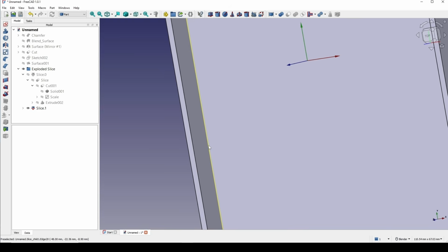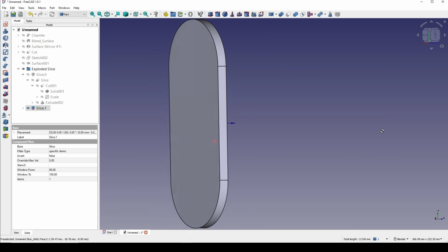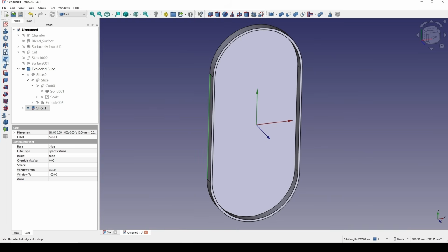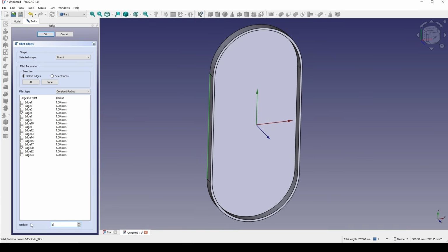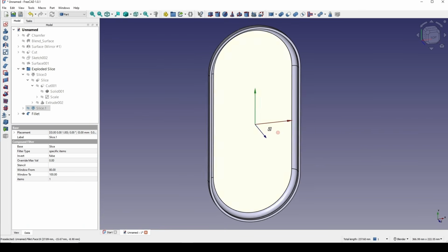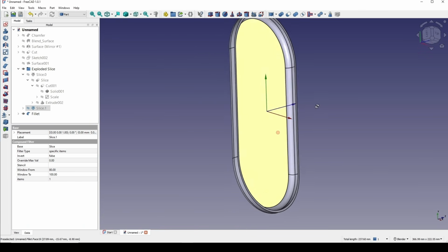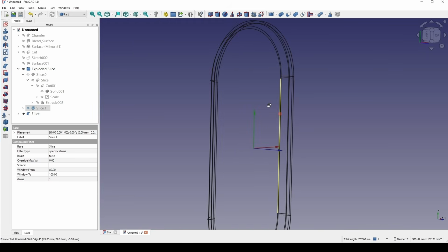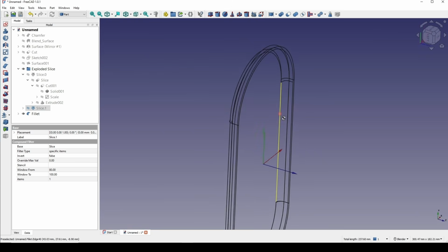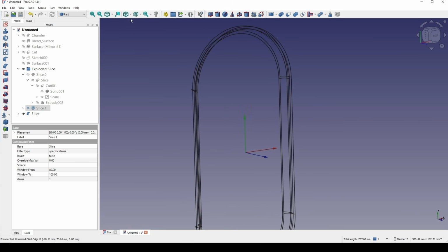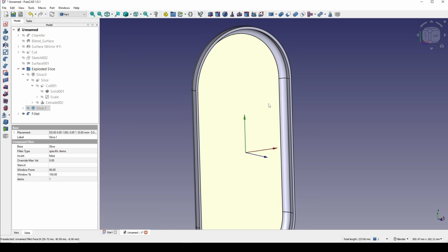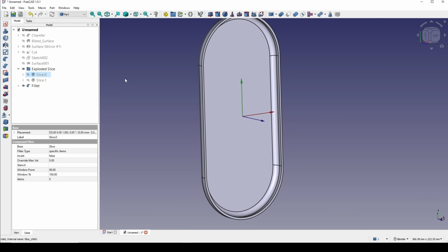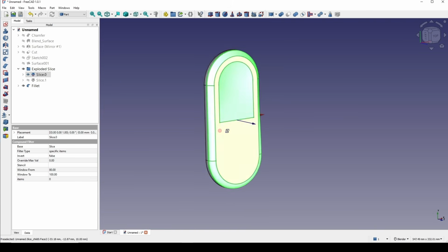Now I can control select this edge inside and this edge outside. And I go to Fillet. Let's try 5 for that. Okay, now it's pretty good. And you can check by going inside the wireframe, and I think it's pretty good. Let's go back here. And then let me go inside here and show the slide 0. All right.